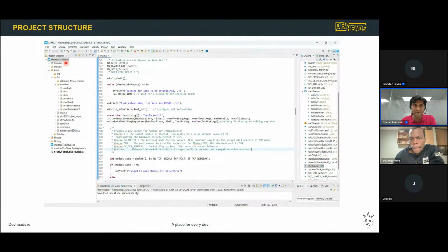live stream episodes. What I have done in the project, while we are writing a program for STM32 to make the Modbus TCP server, is use the IO library from WIZnet, that is for W5500. If you don't know the IO library, go ahead and watch our previous live stream. It's about the Ethernet controller, and I went into more detail on how to integrate this IO library into your STM32 project and how you can create a TCP client and server.